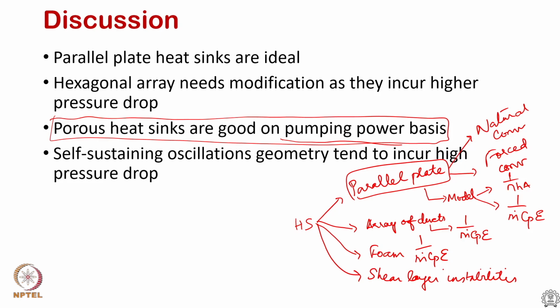In that module, we concluded that for such a situation we need to make use of the adiabatic heat transfer coefficient. The adiabatic heat transfer coefficient uses an adiabatic temperature, which does not depend on the fluid temperature but uses the solid temperature, as a way to come up with an invariant descriptor for heat transfer coefficient.